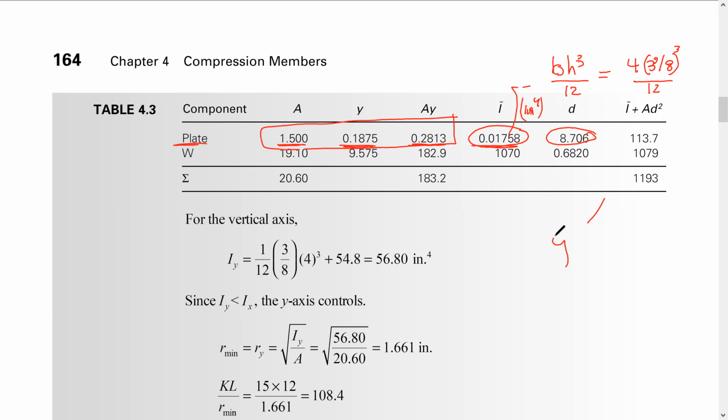Here, guys, it's Y prime or Y hat minus the thickness 3/8 divided by 2, because the centroid of the plate was at the middle, from here. Or let's say it was at the middle when we say this datum, the upper one, is the datum here, and this is statics. So its centroid was 3/8 over 2, meaning half of the thickness.